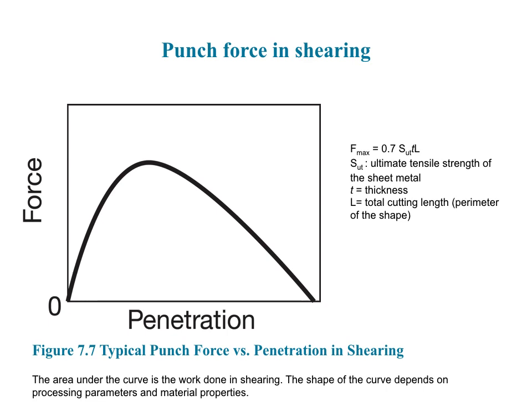Next, we look at the punch force. If you look closely, the force is a product of shear strength of the material and cross-section area being sheared. The friction between the punch and the sheet increases this force significantly. Now, the shear zone is subjected to a combination of plastic deformation, friction, and development of cracks.